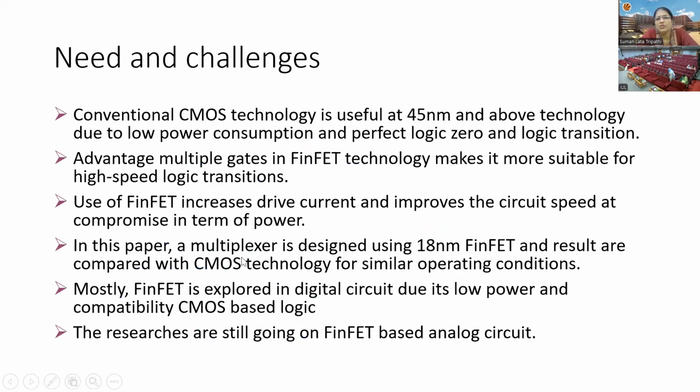Okay, so need and challenges. I already told you that below the 45 nm technology node, the problem with CMOS technology is mainly power consumption, and because of that you cannot pack more transistors for further increase in applications. So FinFET technology or similar multi-gate technologies are trying to replace CMOS based technologies in integrated circuits. And the increase in drive current improves the circuit speed.